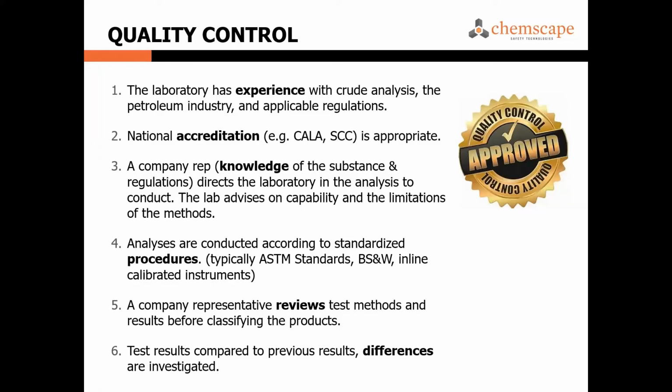Anyway, because I was able to figure that out, I tracked it back to that investigation. Turns out they bought a different type of diluent to mix with that bitumen dilbit. And I was able to alert the process safety people. They didn't realize that they were using a different supplier for their diluent. And they had to do their investigation and make sure that the whole system, the pressurized vessels, were okay with that change. So it was kind of a big slip up, but somebody found it, and we were able to control any further damage. There was no damage, but having that train sit there was probably considered damage.